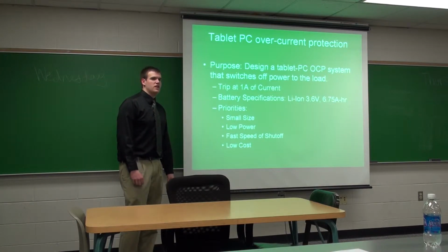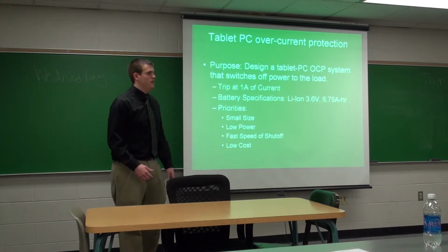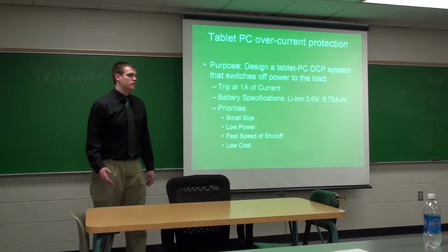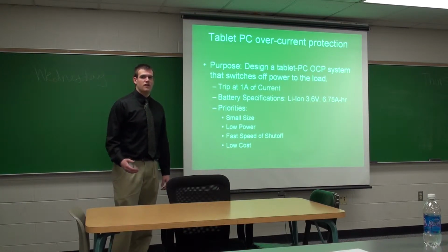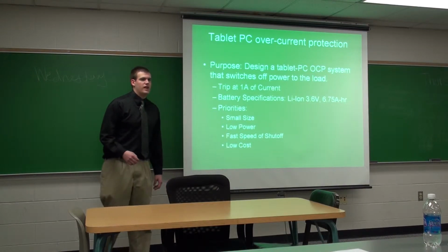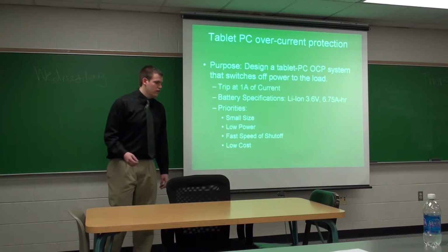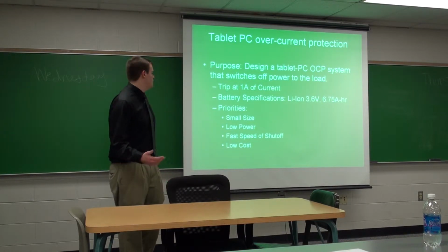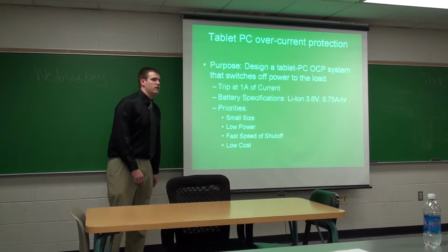The priorities for this application were a small size so it could fit inside a small tablet PC. It has to be low power to minimize impact to the rest of the tablet PC system. And it needs a fast speed of shut off so that if the load were to draw too much current, it wouldn't damage the PC too badly. And it has to be low cost.